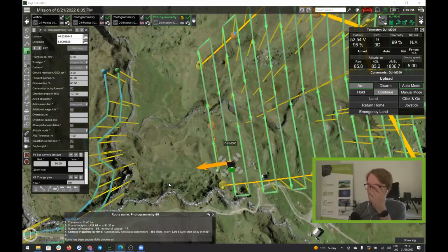as the drone is flying. By the way, just a side note, one other quick and quite useful thing is that when you have your drone flying an automated mission, a DJI drone specifically, I didn't know this for a really long time, but it turns out you can use the pitch stick on the controller to make the drone fly faster or to make the drone fly slower. So if you want the drone to slow down during certain segments of an automated flight, you can simply push down on the pitch stick and then the drone will slow down. Similarly, of course, you can control the yaw of the drone. You can't control the height, unfortunately. We have had this question before, so you can't control the height in those cases.